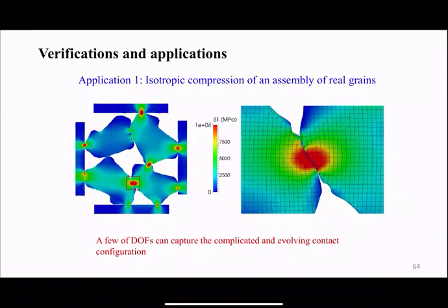However, here we introduce a trick: for all the outer boundary, we simply use a smaller mesh, so that in case there's a stress concentration at the boundary, we can capture the details. But there are other better technologies that we may consider, like edge refinement, or adding more material points to make the stress calculations more accurate, etc.